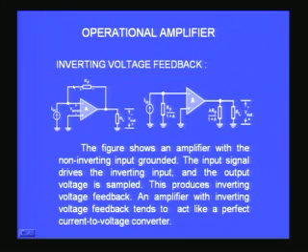This circuit with a feedback resistor can also be analyzed from a known theorem that we already discussed earlier. You might recall the Miller's theorem. The Miller's theorem helps you to split the RF, which is the link between the output and the input, the feedback resistor, into two components exclusively, one at the input and one at the output. You might recall that when I split this RF and put here as a shunt resistance at the input and the output, the shunt resistance at the input will be given by RF divided by 1 plus A, where A is the gain of the amplifier.